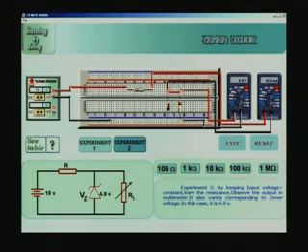If I increase the load resistance, more of the current will flow through the Zener diode and less current through the load resistor. So you must make sure that this division of the input current through these two does not exceed the maximum current possible through the Zener diode, corresponding to the power rating of the Zener diode.